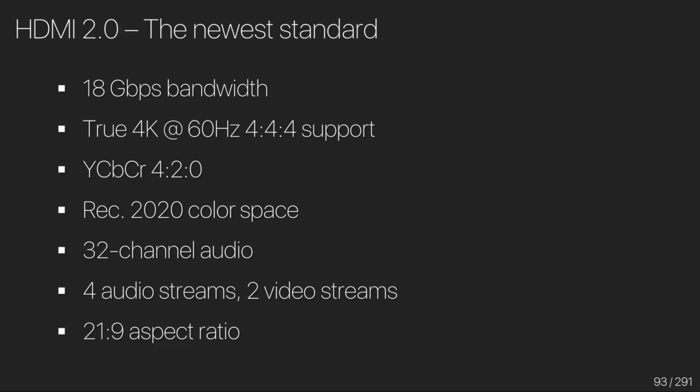One more question. While using EDID management in Lightware, if you're using the factory EDID, and in case the source does not have support for that resolution, what will happen? A lot of times it will revert back to something like 640 by 480. I've seen that happen. So the lowest possible resolution it can use. That's the most common thing I've seen. You might expect it to not send anything, but that seems to be a kind of fallback, particularly for laptops and those kind of devices. If you were using it with a Blu-ray player, you probably wouldn't see anything.